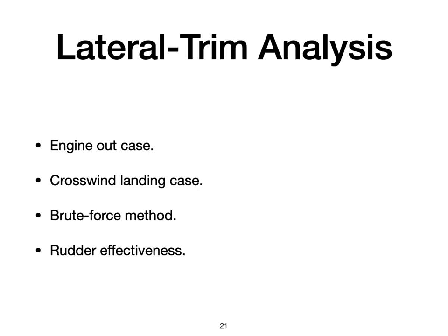It increases the vertical tail size but has an adverse effect on aircraft weight and drag. Last one, rudder effectiveness. Under this, rudder chord, span, double hinged rudder, and all moving vertical tail can be used to increase the rudder effectiveness.